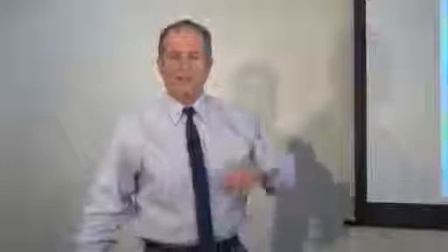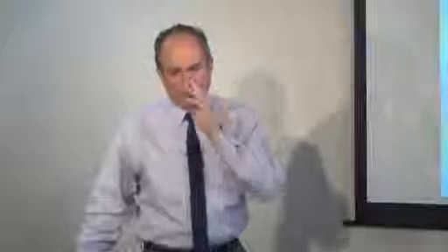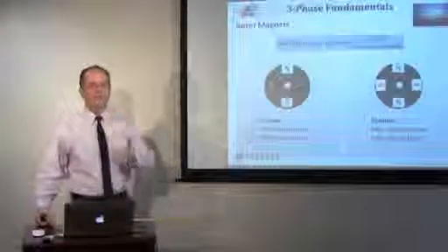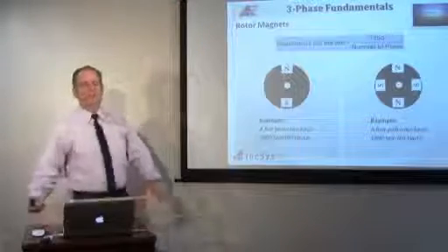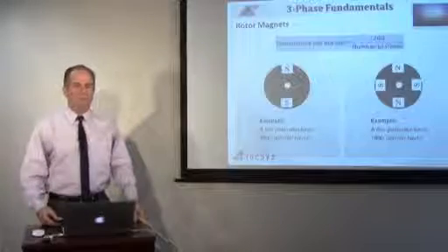And you can actually watch it turn. It's about that fast. Because they have so many poles, it doesn't take very far to have a north pole go through the red, the blue, the green phases, the red, the blue, the green. It comes up so frequently that the shaft speed can be much slower. So I just want to point out that shaft speed can be controlled by the number of poles on the rotor.